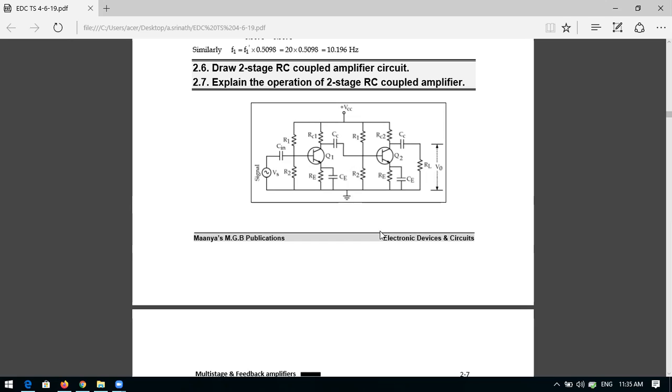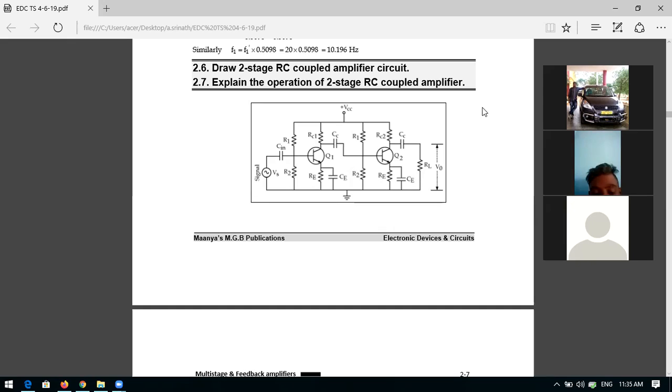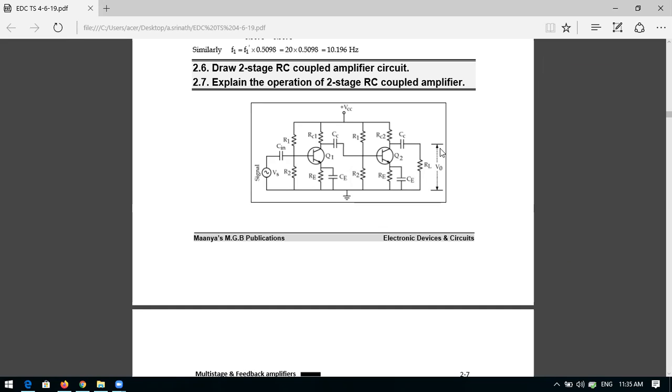The VCC is a DC signal which adds some signal to the circuit. Actually, you want only the AC signal to be amplified. You don't want to amplify the DC signal. That is the unwanted signal which you can call noise. So here DC is the noise. In order to eliminate this DC, you have to add a coupling capacitor in between. So that is the reason you can call them blocking capacitors.